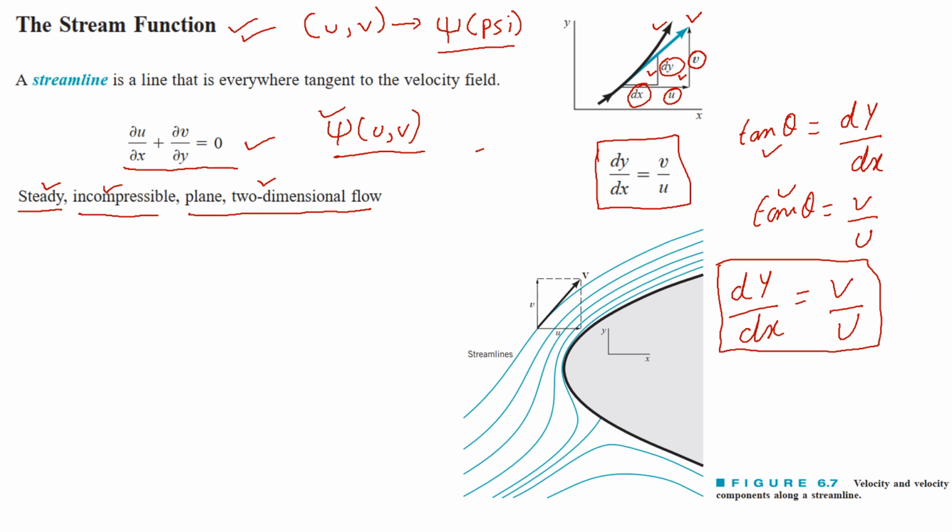Right now you can see that we have two unknowns, that is the u velocity vector and the v velocity vector, in this single equation. So by representing these two velocity vectors by a single psi term, we can actually get one unknown and one equation. So let's see how we are going to use this psi term.